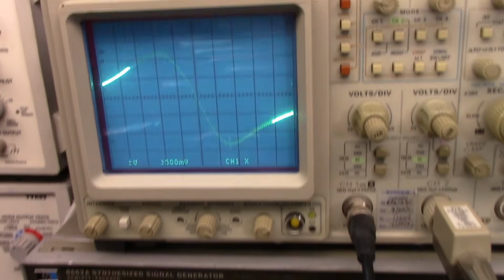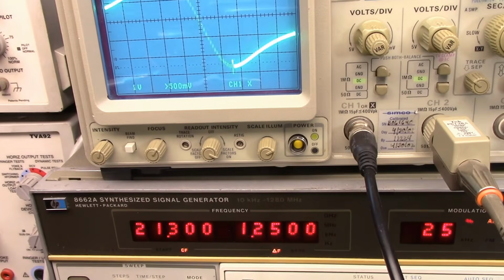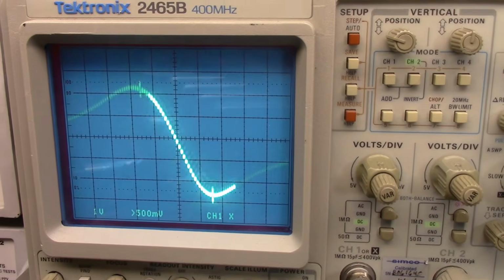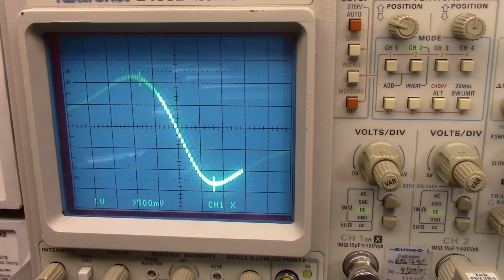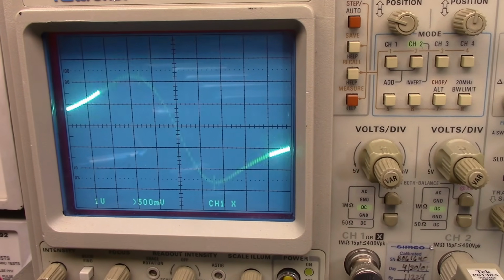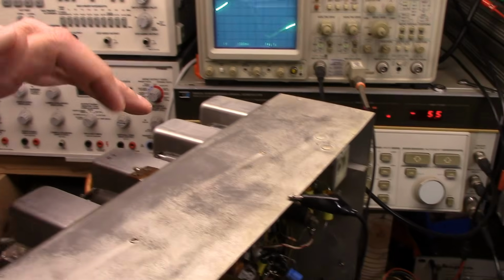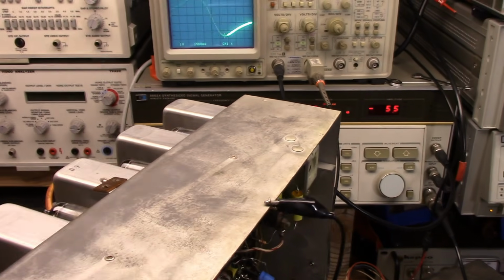I'd say that's better. I did increase the delta frequency from 1 to 1.25 so I could see a little more of the overall response. I've got the peaks pretty well where they're supposed to be, and it's crossing over in the center, so we can proceed to the earlier stages now.